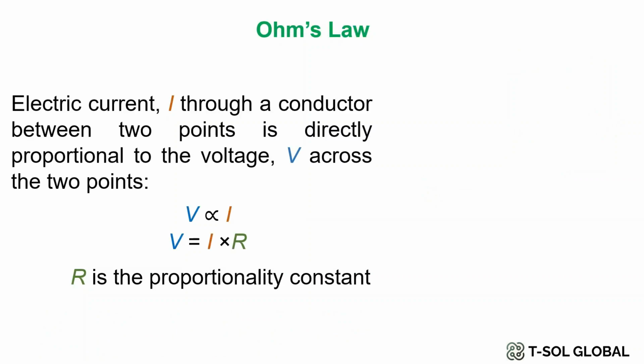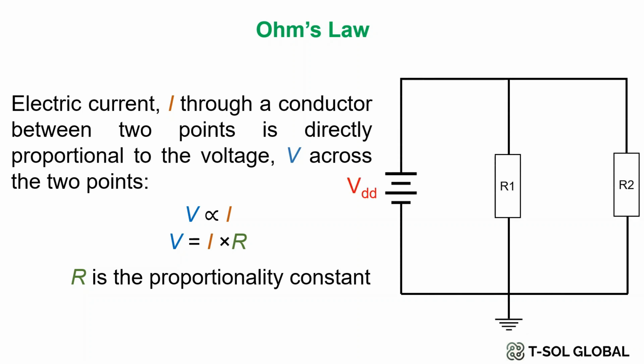Next, with the same Ohm's law, we are considering the second example circuit, where it has a DC source and two resistors R1 and R2 in parallel, where we are considering the R1 resistor. V1 is the total voltage drop across R1 and I is the total current of the circuit, where I1 is the current flowing through R1.